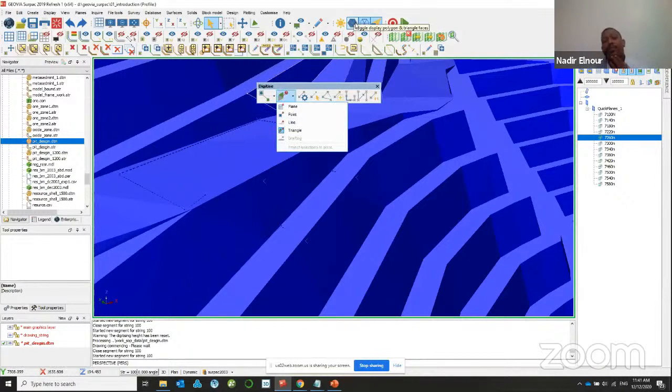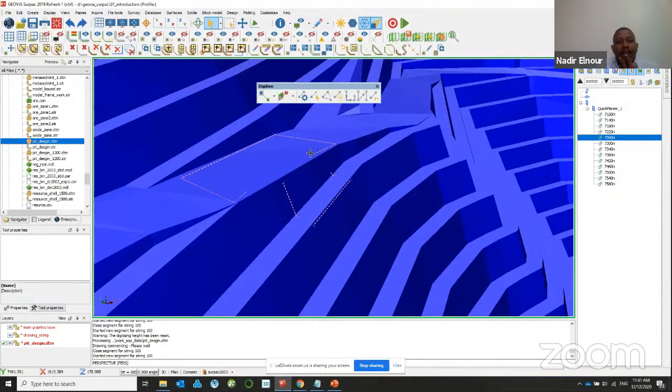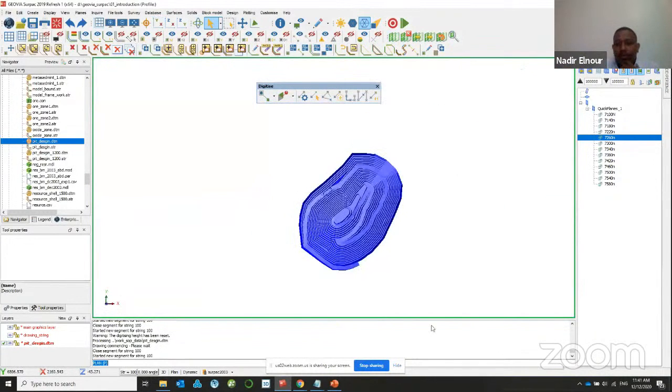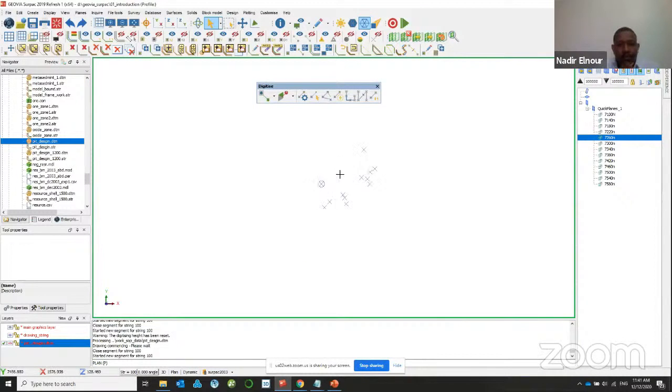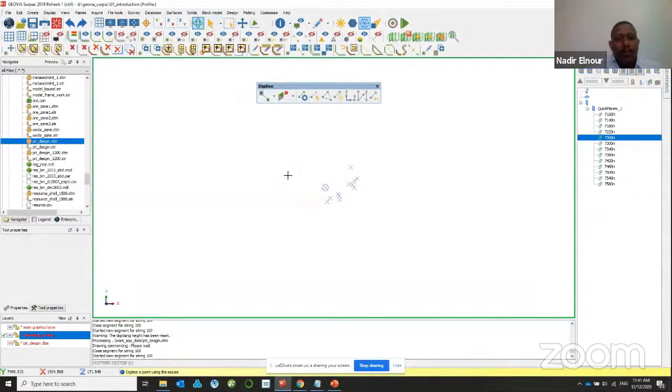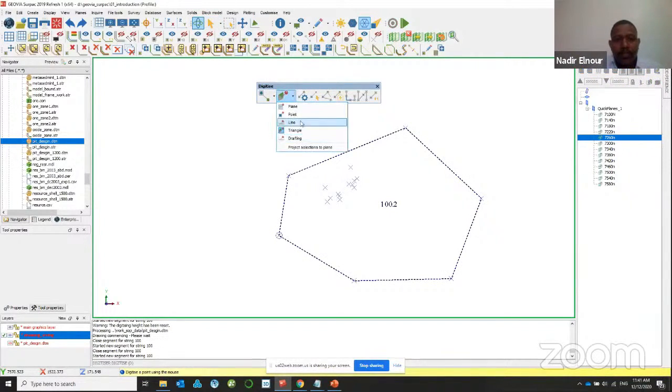DTM. And also you can snap to line. For example, if I would like to go and snap to line, so if I remove this one and then come here, and I have already drawn a line. So for example, if I need to draw another line and snap to that line, I need to go here and just snap to the line, and then once I click, it just snaps to the line. You can see it just snaps to the line.